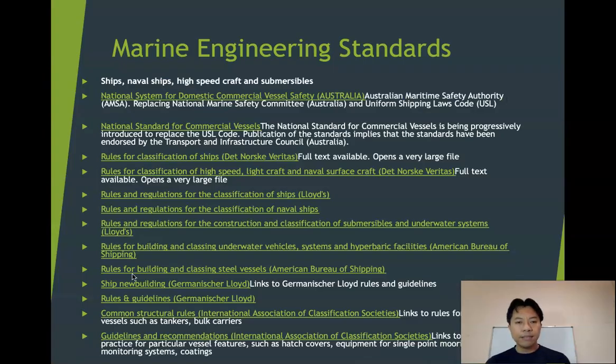For marine engineering standards, we have different standards that we can use other than generic mechanical engineering or electrical engineering. So we have standards for ships, naval ships, high-speed craft, and submersibles. We have the Australian Maritime Safety Authority, or AMSA, that replaced the National Marine Safety Committee of Australia and the Uniform Shipping Law Code, USL. If you are building bigger vessels, you have the National Standard for Commercial Vessel.